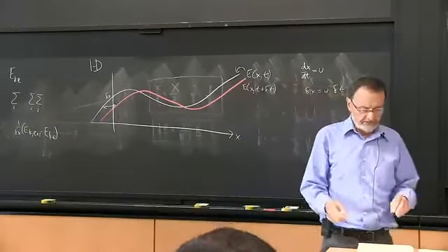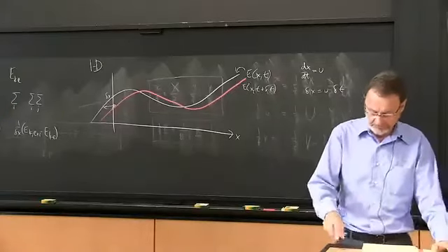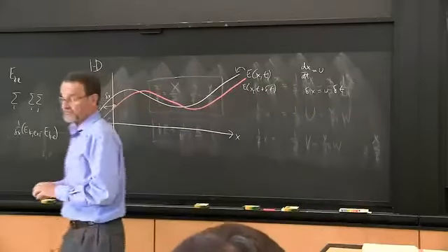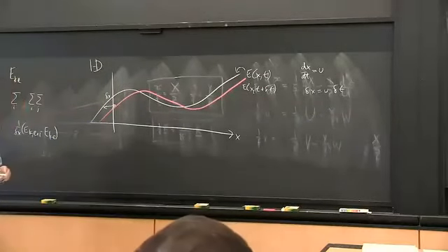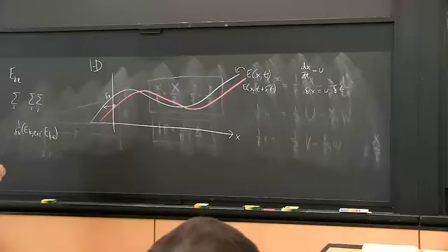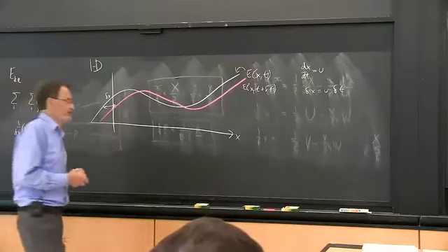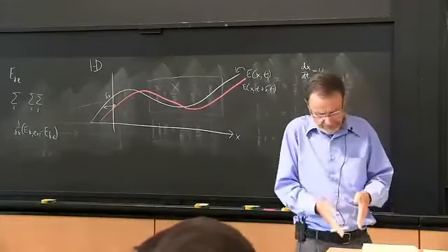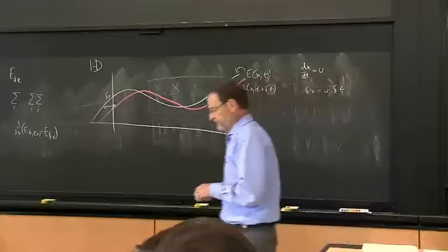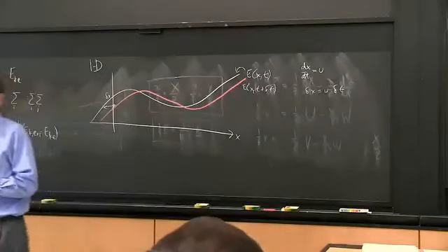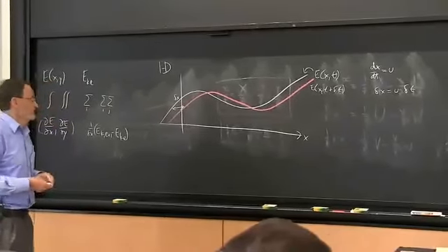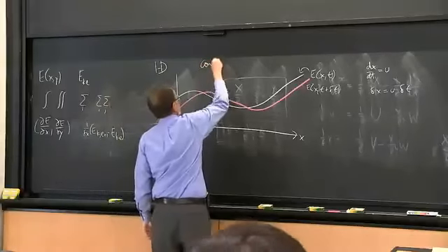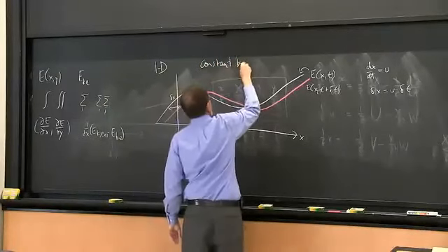One of them is that the brightness doesn't change. If your optical mouse is looking at the surface of the table, then presumably between one frame and the next, the illumination isn't changing. It's using an LED with a constant current, and it's taking 2,000 frames a second. So it's unlikely to change. The geometry is changing a little bit because you've moved and now you're looking at the surface from a slightly different angle. But for most surfaces, the change in brightness due to that is very small. So right here, the way I've drawn these curves, I've assumed constant brightness. So let's get it right out front: constant brightness assumption.